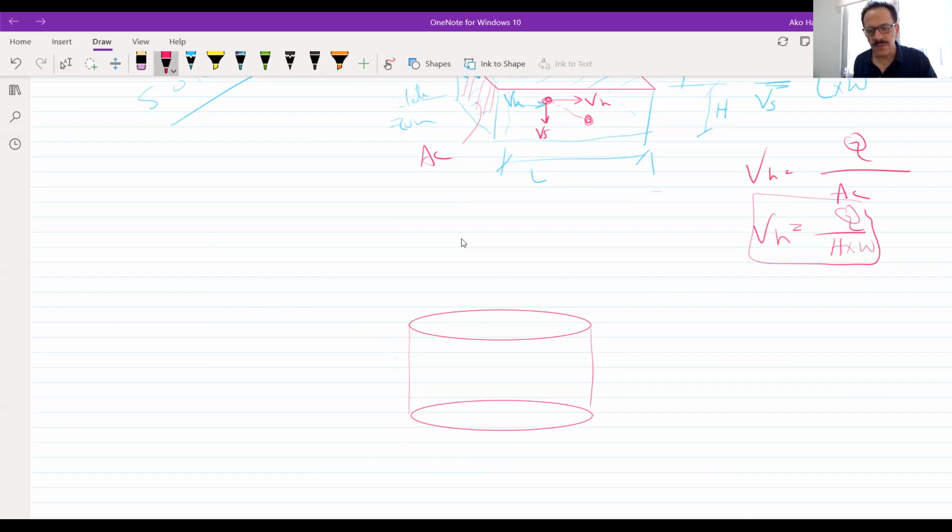The water is coming from the bottom until we have an area like this, and then the water is coming down from this inlet. Now, we said that if there is a particle, this particle is going to settle down. It will stay here. So this particle will settle by the effect of gravity, so it has a settling velocity like this. And it also has a horizontal velocity VH.